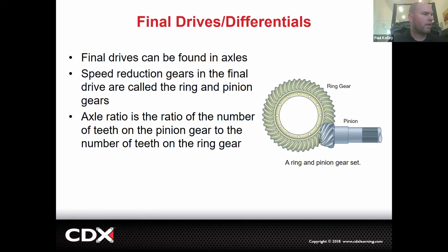It was in that video. And the answer is, if we brought it right at the middle, right at the center line, that drive shaft would be up higher. You'd have to have a big hump go into the rear seats, or you'd have to run the shaft inside the vehicle and have little kids get wrapped up in that shaft or something. So we had to drop the shaft down to give a nice flat floor for the passengers on those older, like 1930s and 40s and 50s vehicles, because they were all rear wheel drive.